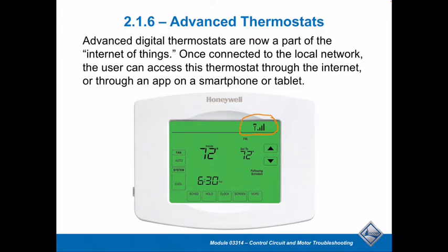However, in commercial jobs and some residential jobs, we might have a line voltage thermostat that they might control using either a pressure sensing bulb, or what we call hydraulic sensing, or it could be a bimetal sensor. And we might use it so that, as an example, if it gets too hot in this room, we're going to energize an exhaust fan.